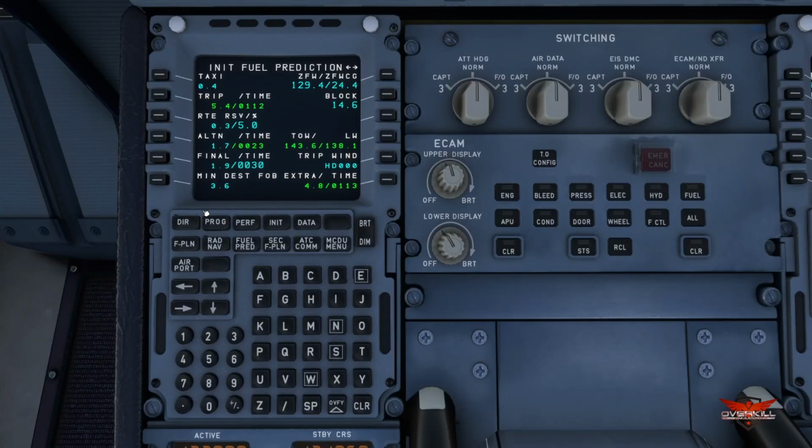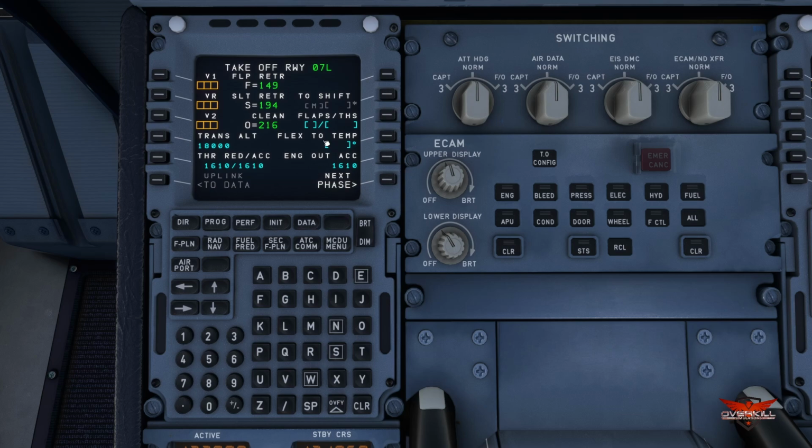So what do we do with that information? Now we're going to go back to our performance page here, and under flaps we're going to be using flaps takeoff 1 slash, and then we're going to do 0.9. Now here's the tricky part, up. Got to make sure that you tell it which direction you're doing with that trim setting, and boom, up 0.9 degrees. There's our trim setting. And then now next we need our Flex To Temp. So let's get on to our next tool.